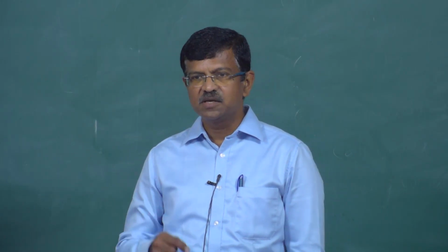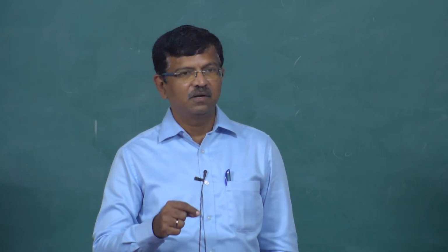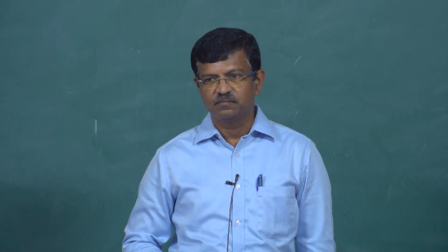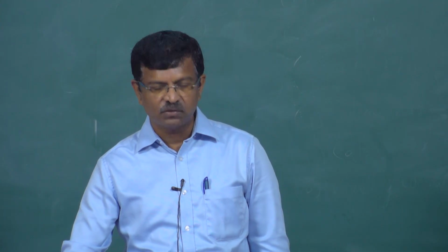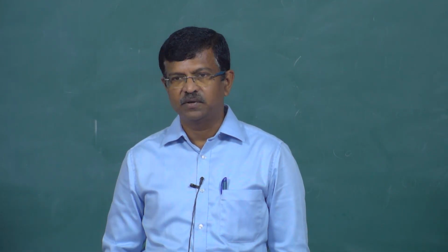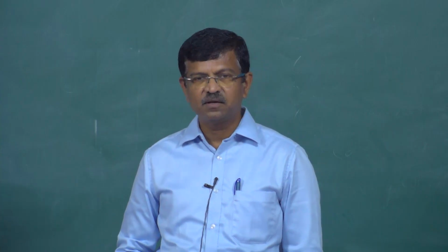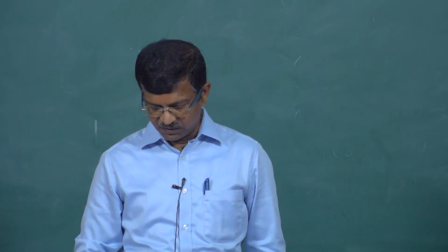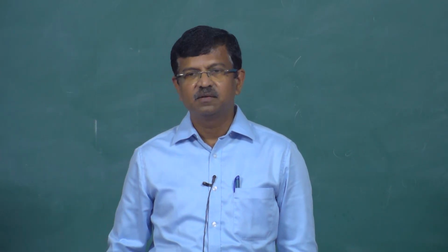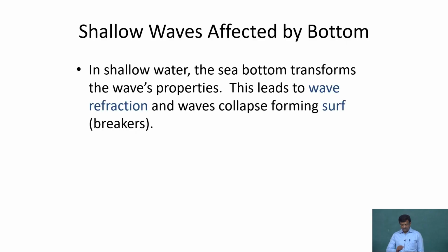That means the seabed will get influenced or driven by the ocean wave. This water particle velocity will make the sediment drift from one point to another point. So, that is one of the very reasons that we divide waves into deep water waves and shallow water waves, which is also important in terms of moving the sediment. And when this water particle motion is influenced by the seabed, that means the seabed will alter the waveform.